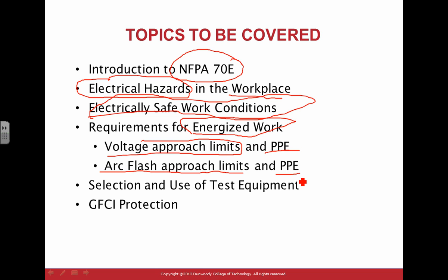If you're dealing with 120 volts or less in an enclosure, do not expect the ball of fire to be 3 feet in diameter. Expect it to be half an inch, maybe a quarter of an inch, a tiny little thing. You'll see it, guys. There is a little ball of fire, but not like a 3-foot ball of fire. So we'll talk about this one.